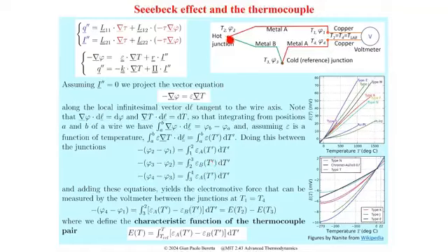And then, of course, since at the junctions there is electrical continuity, the electrostatic potential is always equal. And so now you can add these 3 equations. And what you are left with is this: that phi4, so voltage at 4 minus voltage at 1, is equal to this integral from 3 to 2.